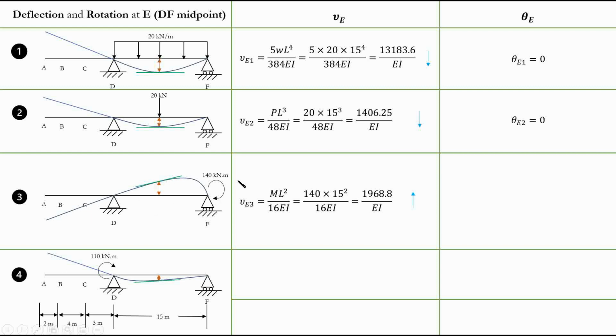And if you cannot find it, you will probably find this formula. However, in some of the books, I've seen that they don't have the center value. They only have the maximum. In this case, you can basically use the general deflection equation, and for the x value, you can put half of L, which in this case is 15/2 or 7.5 meters, and find your deflection. So both of them will give you the same result, but obviously if you have the center option, basically the deflection in the center of the beam, just use this formula and find it.